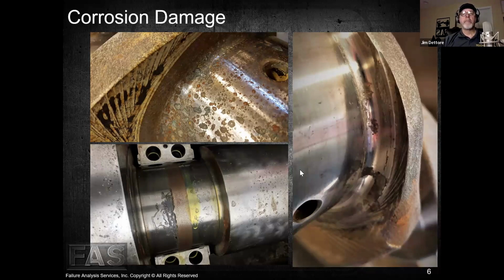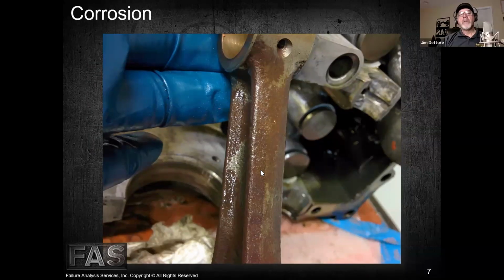It's important that when we assemble components we wear gloves when we're touching bare steel surfaces, simply because of the oils and the salt in our skin, which can be a whole lot worse when we get into the deep South, places like Mississippi and Louisiana and South Texas.